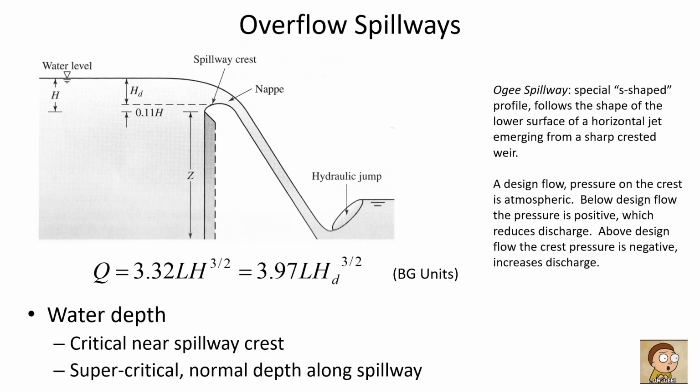So in the video we watched, it showed how the gates could be raised or lowered to artificially increase or decrease the resistance of flow over the spillway crest. So this is just a passive way of accomplishing the same thing. The flow over the spillway crest is a little bit faster and easier than it ordinarily would be at the higher head level because the pressure is reduced.